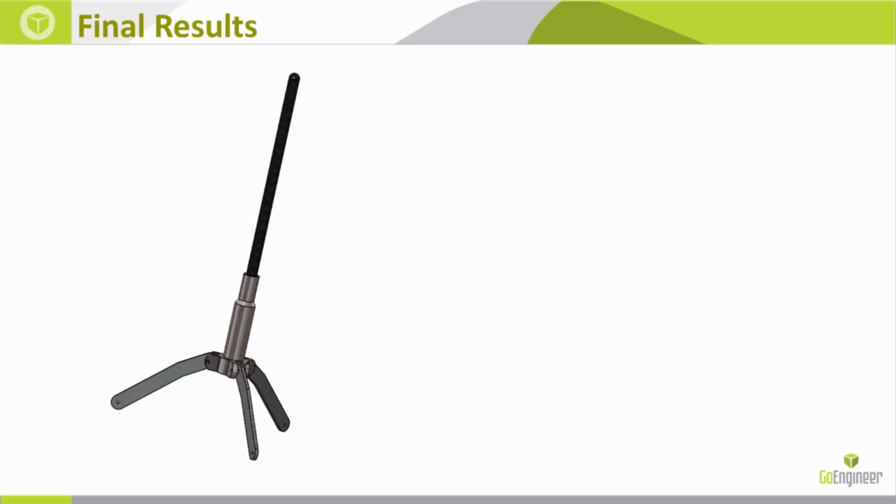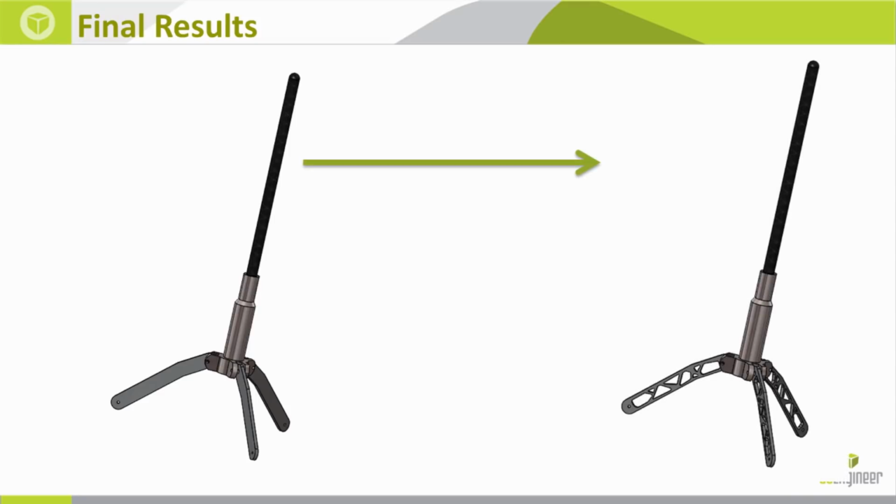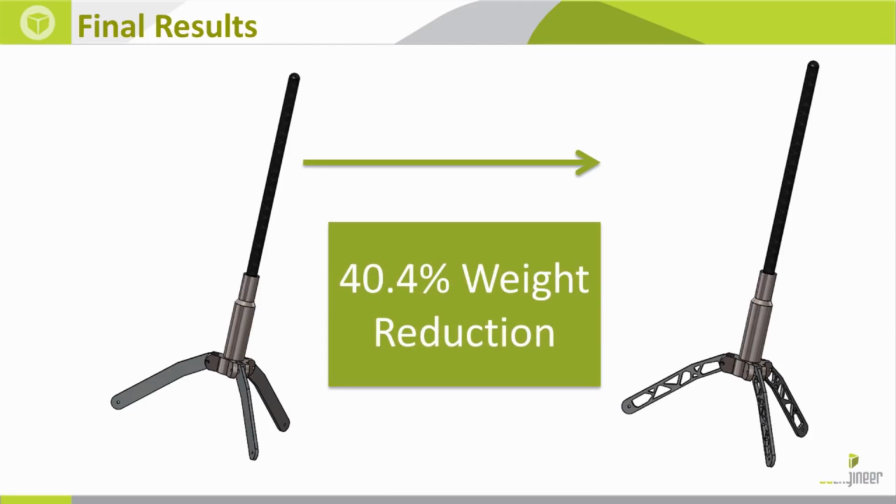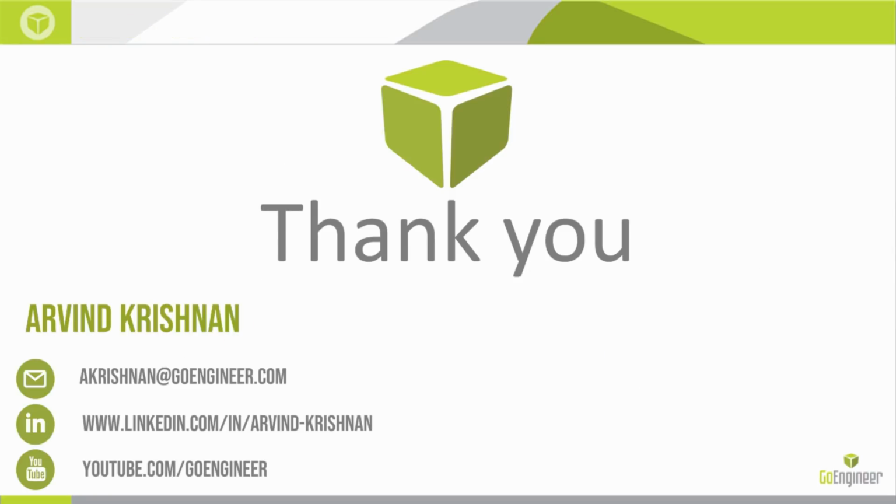So that was my initial design, and we went ahead, made some changes, made it much lighter, and now the new design is about 40% lighter, but it still has a factor of safety above 2, which was the original design requirement. That is topology optimization in SOLIDWORKS Simulation.